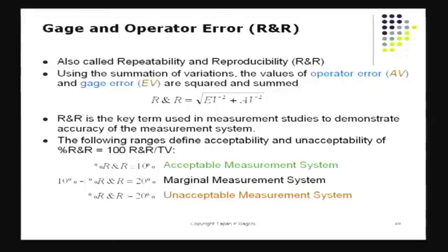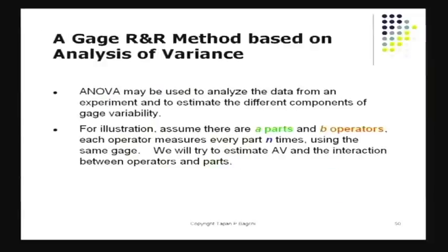In certain cases, the measurement system itself can be totally unacceptable, like when the gauge readings turn out to be contributing almost 20% of the error in the final variation. That's not such a good picture. And you've got to make sure your parts, which is what you are really after, are measured correctly.